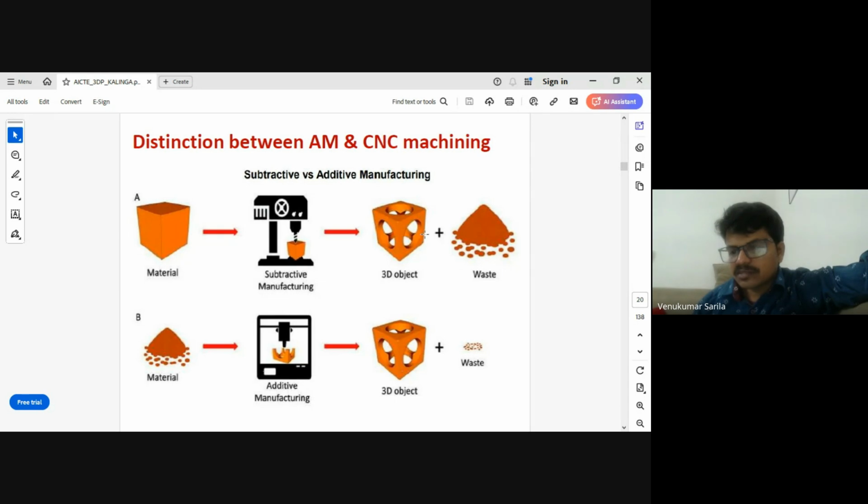The next step is you have to make holes. How will you make this drilling? In the drilling process, there is a drill bit, and we should take a higher strength material than the workpiece. This is the workpiece, you have to make the drills on it, and this is the cutting tool. You give it some rotational speed, and it will plunge into the workpiece, so that you can see the result after drilling. There is a lot of wastage of material.